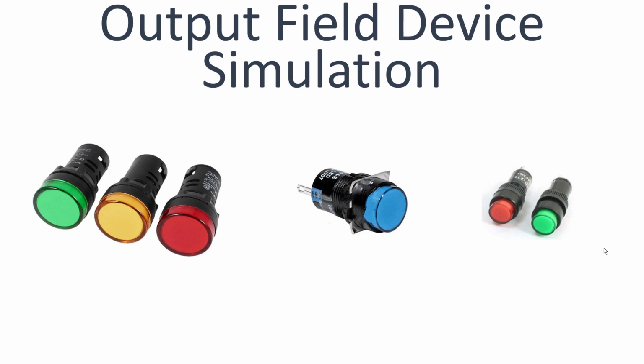I will warn you though that the smaller they are, the less heat they can handle when you're soldering the lugs. The first 3, those have screw terminals, but the second 2 have solder lugs. One thing I really like about the one in the middle is the holes in the solder lugs are big enough that you can coax 3 22 gauge stranded wires into it, so that gives you better wire management. In other words, you can use those lugs to land more than one conductor.